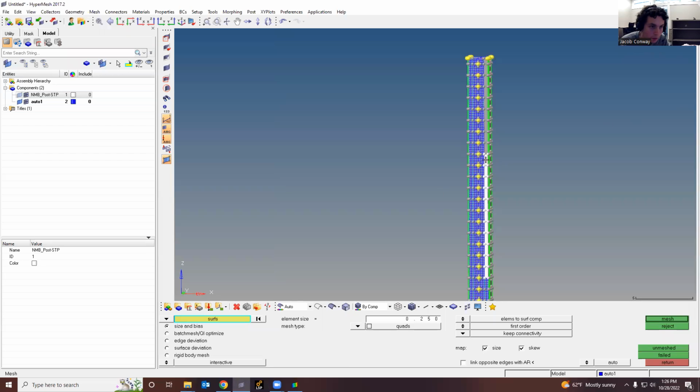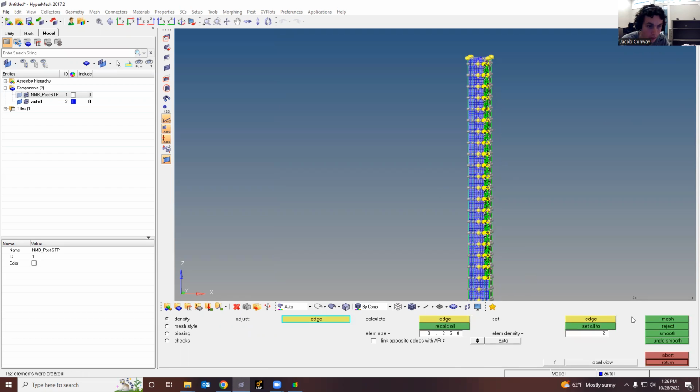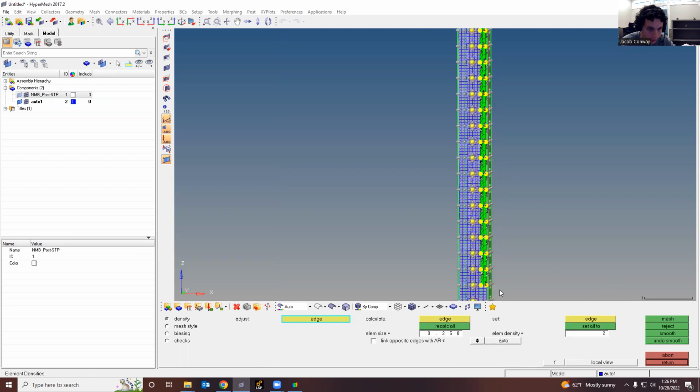All right, so I'm nearly wrapped up here with this one. Just showing you guys my method for these outer ones. Real quick, I'll mesh these, set them all to 2. Since that left side is restricted to actually meet up with those other elements, that stays 5. So then I can just go along this outer edge, go up to 5. And keep this up.